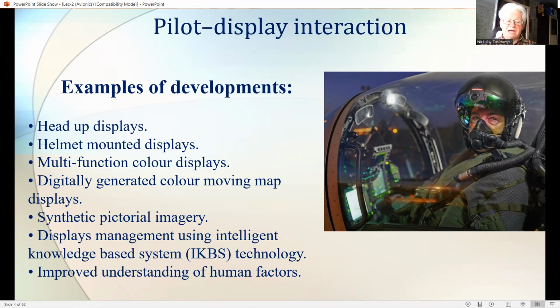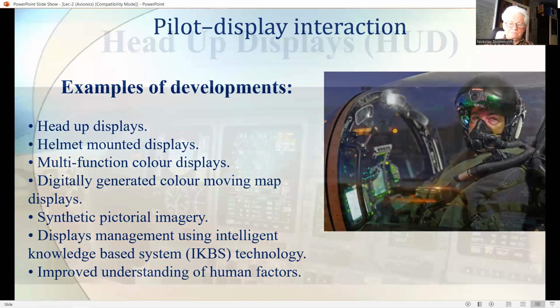The integration and management of all the display surfaces by audio inputs enables a very significant reduction in the pilot's workload to be achieved in the new generation of single-seat fighter or strike aircraft. Other methods of data entry which are being evaluated include the use of an eye tracker.